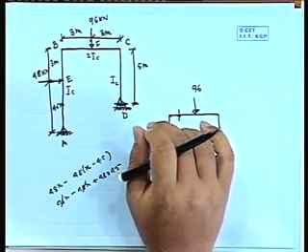That can be obtained if we apply one unit of force or moment at that point, and we get another set of expressions for moment, which we define as small m. This capital M and small m we multiply and divide by EI. If we integrate over the entire length of the structure segment-wise, we should get the deflection at that point or the slope at that point.